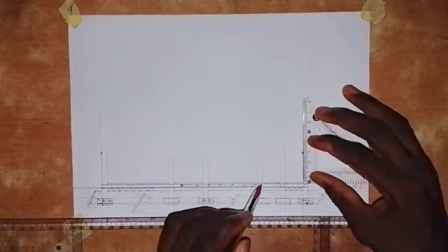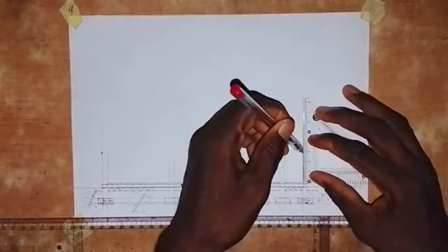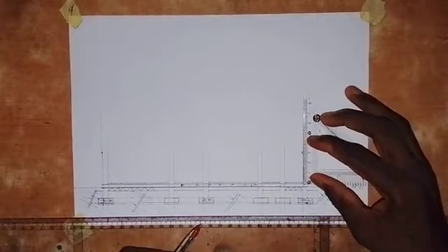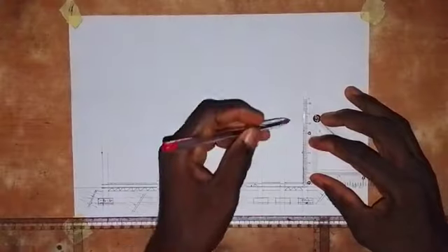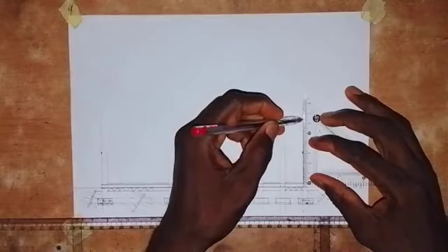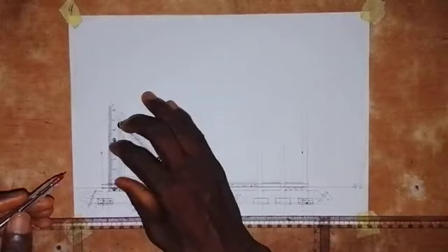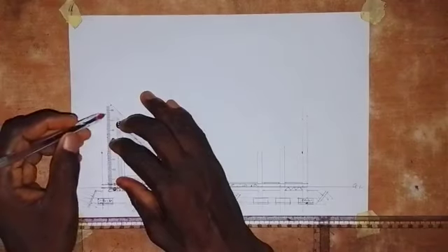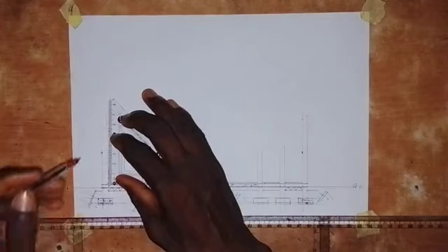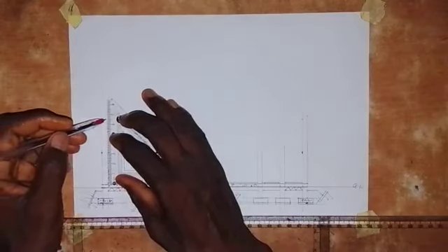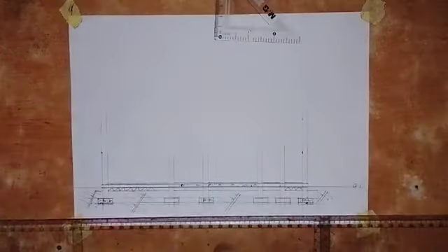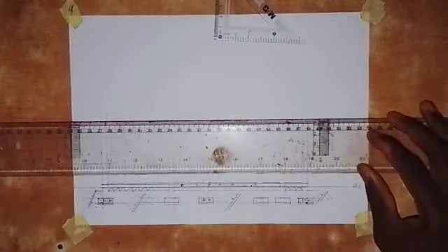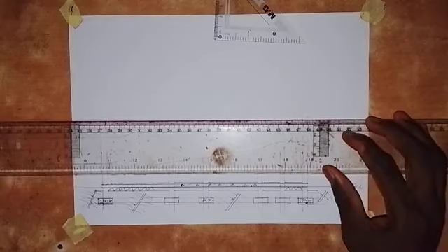That is where we put the screed. So we take a measurement of 64 millimeters up. So here we are 64 millimeters. I will also come to this side and extend this line up, and take a measurement of 64. I want that line to be straight. So this is 64 millimeters. I'm going to join these points together, so I'll draw a horizontal line here.